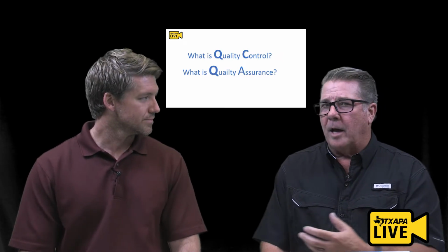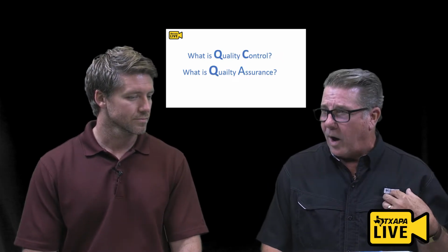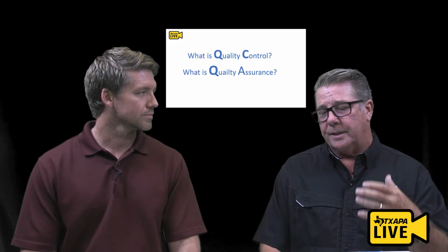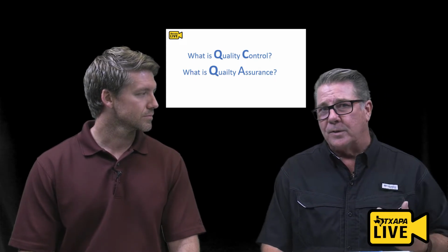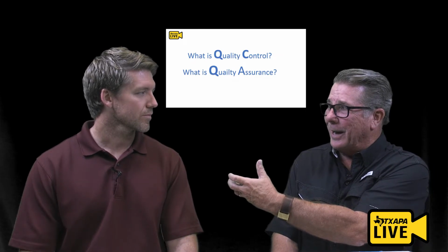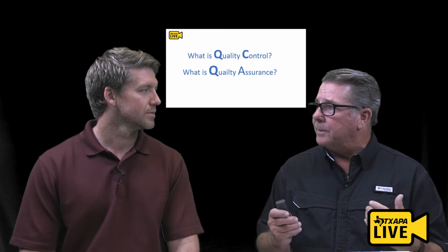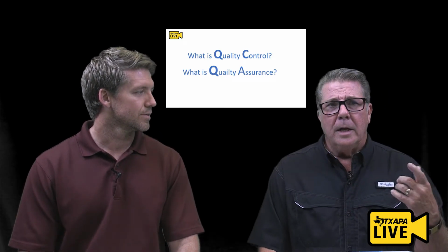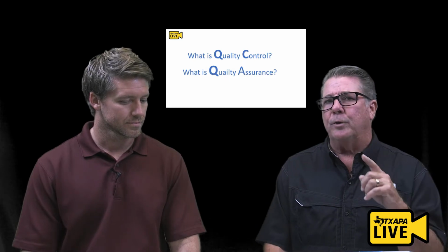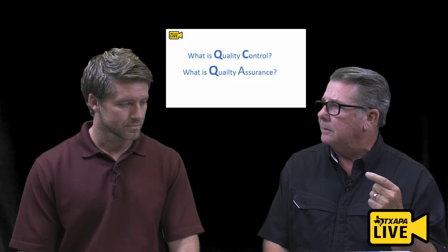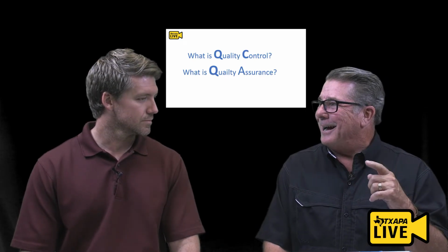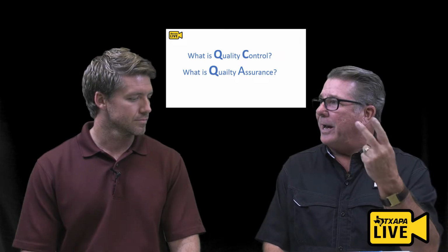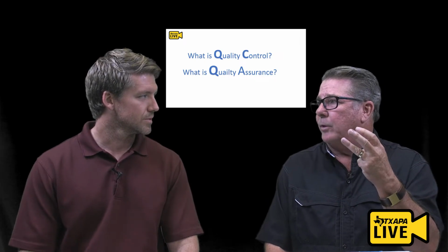That's right. Now, me being QC, I have a requirement that I have to run certain tests at certain times, but my results are only utilized to be able to see, when you get QA results, whether or not we have a discrepancy to be able to go to referee. That's right. So does QC have to run lab densities? So lab densities, I noticed that we have to run ACs and we have to run gradations, but we don't necessarily have to run lab densities.